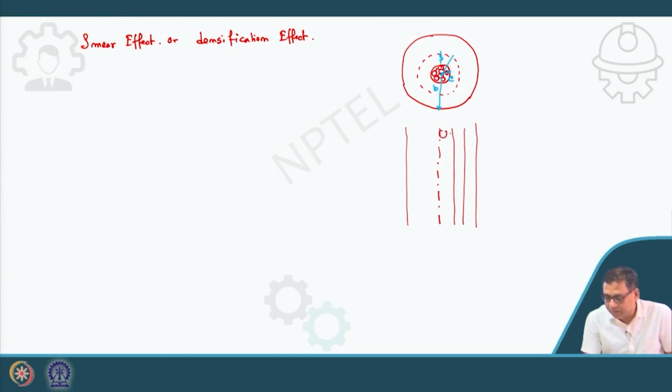So this is B, this is C, and this one is the small s, the smear zone. Now if I draw the vertical section, this is the total influence zone. If I take the half portion, this is our column, this is our smear or disturbed zone, and then the undisturbed zone.